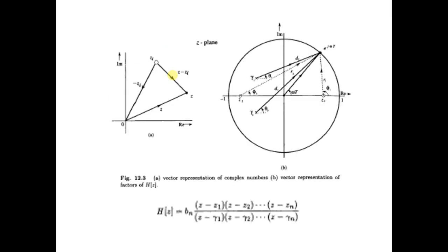Now, with this knowledge, if you come into the Z plane, same distance logic and all these things, we have just introduced a unit circle, and we know that frequency is on this unit circle. So our point P, which we were discussing in our last case, will now be varying onto the unit circle. It will start from 0 and go up to Fm, which is pi. Since we are in the Z plane, S is being replaced with Z. The equation remains the same.